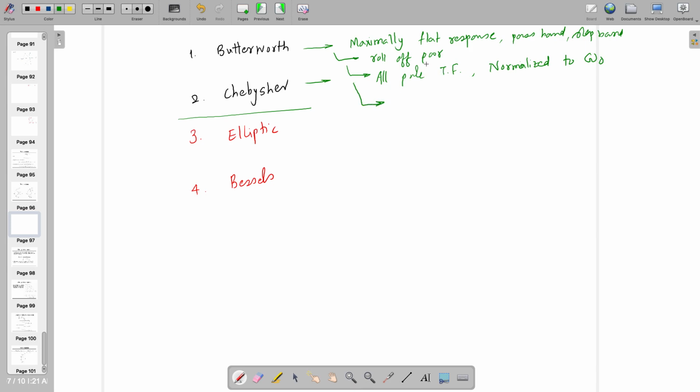All the pole values are coming exactly on the unit circle, and all the poles are apart from each other by (2k minus 1) pi by 2n, where k is equal to 1 to n. Right? So it would be like this.